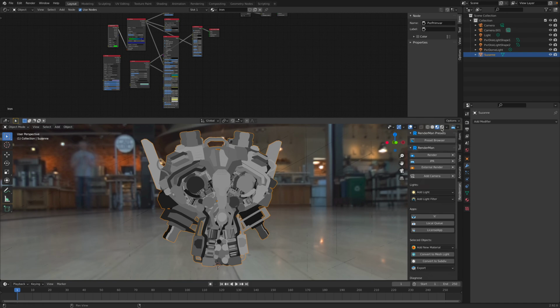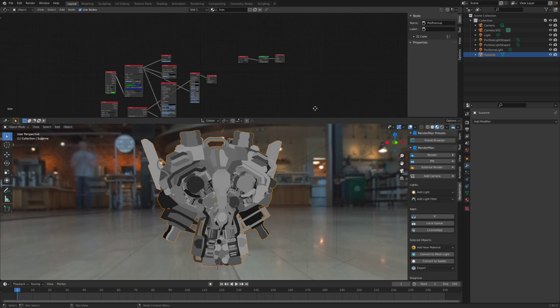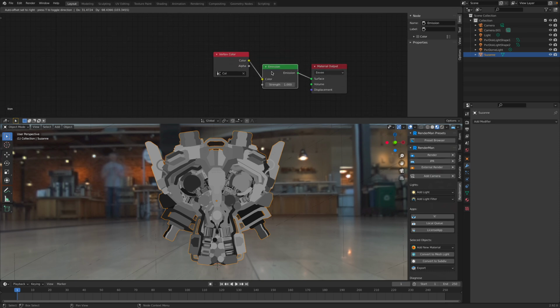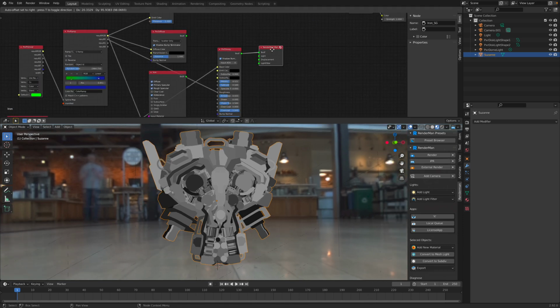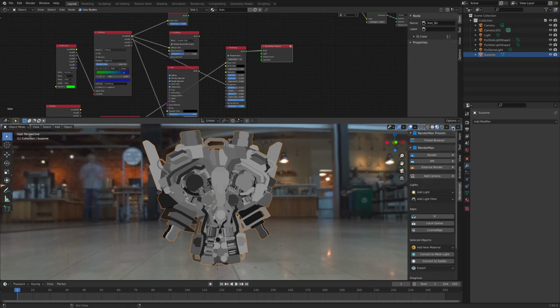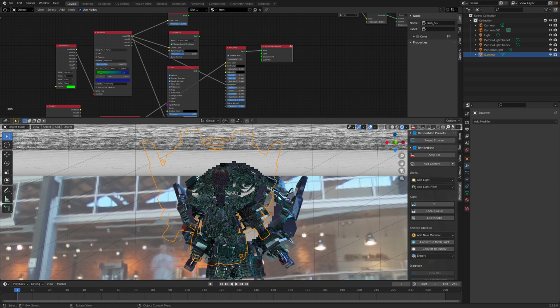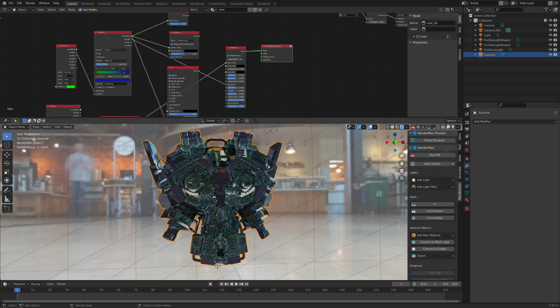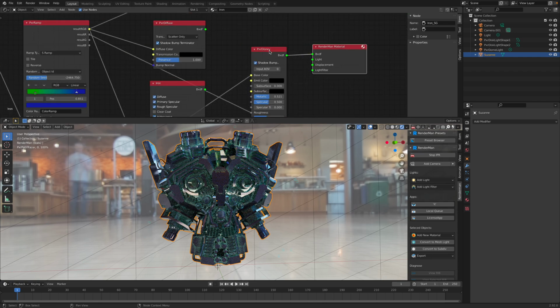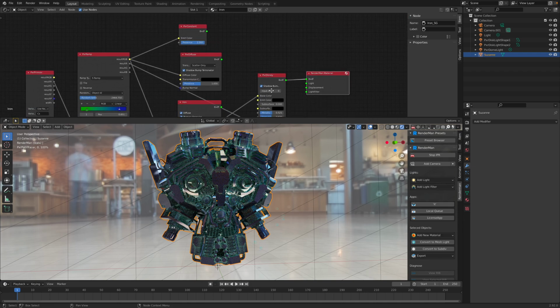Now if we switch to RenderMan, basically the shader I have for this goes into Eevee. We can also use Cycles, but Eevee is for real time, and we have this RenderMan BxDF that's going to render our 3D assets here. This is the IPR render of the object. It takes some time to calculate until the noise starts to disappear, or we can use denoising. This is what I want to show you. This is using, I think, the Pixar Disney shader. I can also use the Pixar shader material.